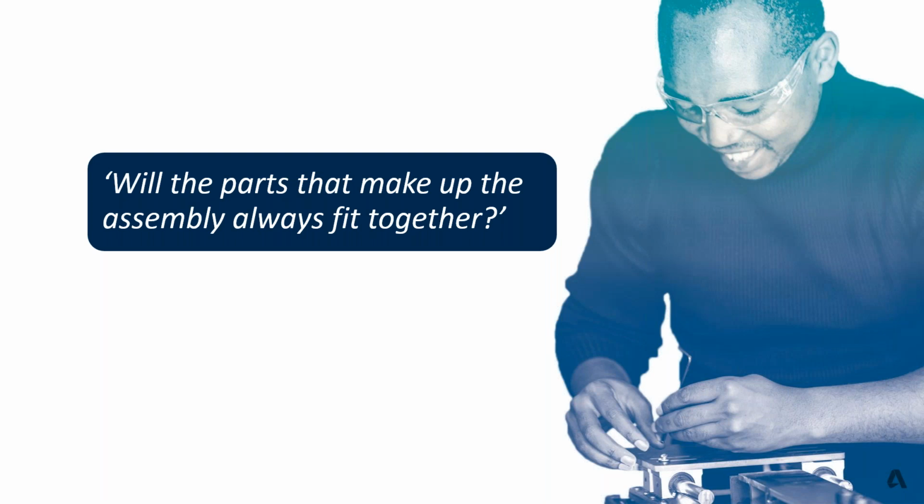Materials, equipment, tooling, environment, and operator inconsistency can all lead to slight variations in size. We know that, we've seen that before, we've heard of cases before in the past. Individually, this might not be a problem, but incrementally, these variations can stack up, preventing parts from fitting into the assemblies. They become scrap parts. Now, depending on the tolerance or the precision that you're working with, going off could be very critical to your manufacturing process.